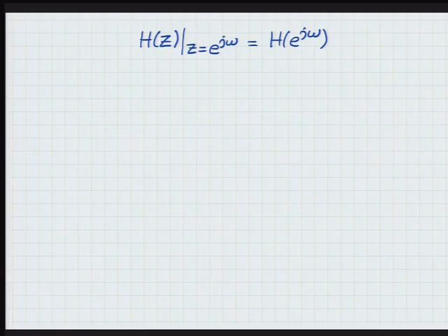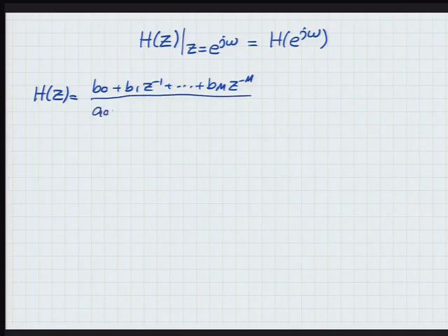All right, so we're going to look at what to expect. How do the poles and zeros of the transfer function affect what the frequency response is going to look like? So let's say I give you a transfer function H(z) that looks like this. That's the general form we just discussed, associated to difference equations, b_m z to the negative m. And then you'll have similar terms in the denominator. How many zeros does the system have? Capital M, and it's going to have capital N poles, right?